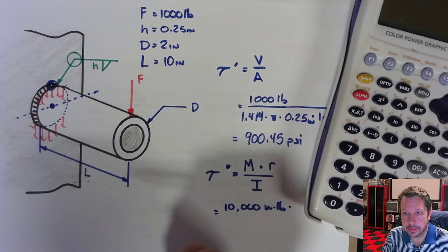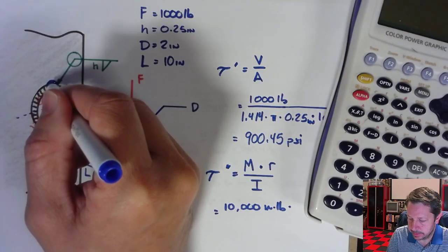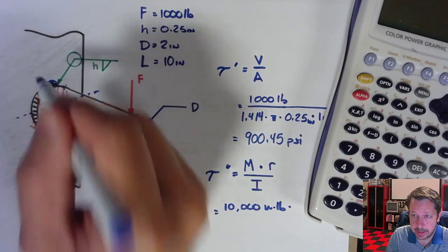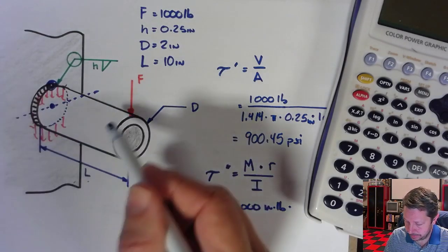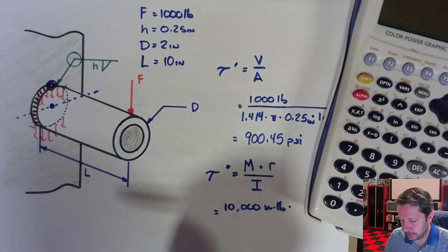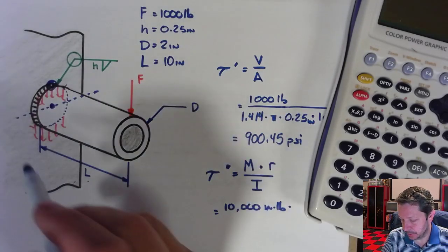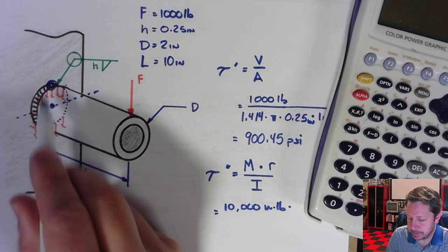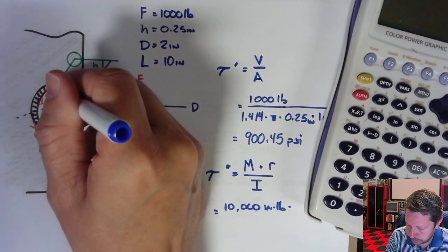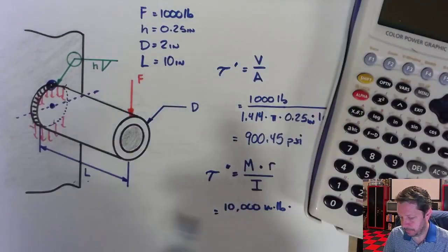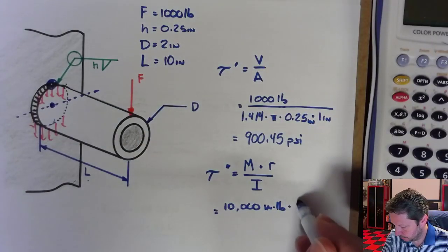That's where I believe the worst case would be. If I'm pushing down here, there's a good chance it could pull away from the wall at the top. On the bottom, it could still break the weld, but if it did, it's going to push it into the wall, and it would still hang on there, assuming there's some weld at the top still. That would give me the same exact numbers that I'm going to calculate here anyway. So the distance from here to the top of the weld is my radius, which, with a diameter of 2 inches, is 1 inch,